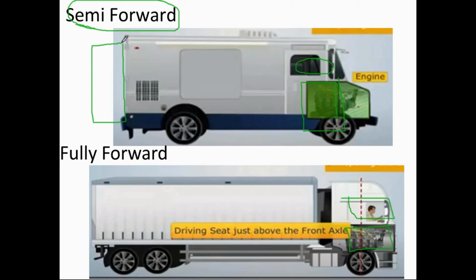The backspace which was present behind was increased. For different containers, you can observe the total engine is mounted below the seating arrangement. If we don't require maximum space over there, then either a semi-forward or a conventional type of automobile vehicle will be preferred. The fully forward vehicle is most probably preferred for heavy duty vehicles.